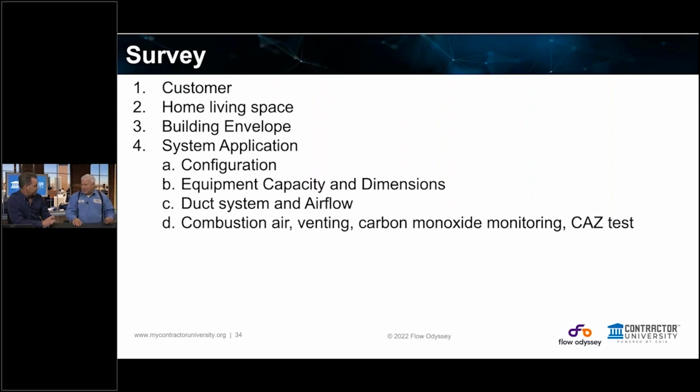Wow. Okay. So were those commercial buildings? Yes. Yeah, because obviously where we are, right? Right. But commercial, this is residential. When I took my walk, I saw over a dozen houses that had ice off the flue. Okay. And that's a call for action. There you go. Right. So that means the flue gas isn't getting warm enough. Yeah, and we're obviously in a super cold climate. We've had a little bit of snow here, and so you're going to probably see that a little bit more in a place like this, and maybe in certain other markets.